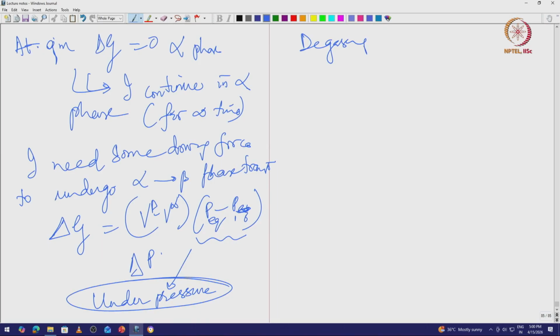If I reduce the pressure too much, then I will degas a lot, right. This is what happens at very low pressures: my materials start to degas because they are starting to vaporize, right. The gas phase is starting to form, and that is the idea of degassing. You have to consider this because low pressures would favor degassing. So, the lower the pressure I go, to UHV, the more I am degassing from my solids. That is what thermodynamics would dictate.